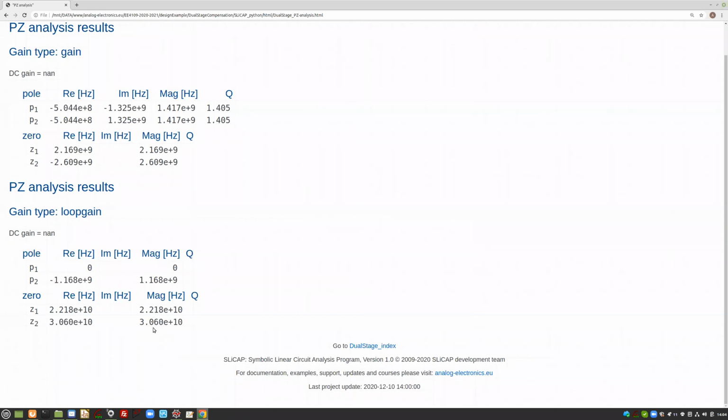And we will see later on that if I calculate the frequency compensation for the case in which there are no zeros, there's only two poles, that I will be a little bit off with the result. We need to correct it a little bit because of the effect of the phase shift caused by the zeros. But for now, we're not yet talking about compensation. We were just checking the bandwidth, and you see that our hand calculation that you can really do with a simple circuit closely matches the result. And that is the message of this presentation.